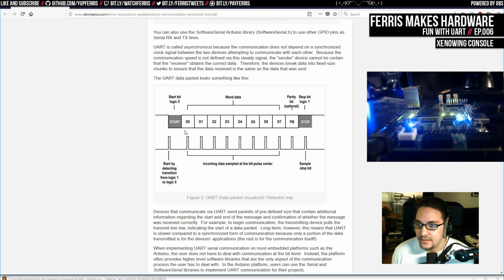And UART is a really simple protocol. You basically have the bit rate here, which is the timing between different parts of this protocol. That's already predetermined. Your transmitter and your receiver just have to agree on that. In this case, I'm just using 9600 baud, which is baseline. It's total crap. I should actually be able to raise that because I think the chip on this board supports up to like 2 megabaud, which would be a lot better. But I think I need to update drivers to do that, and I just haven't bothered yet. I wanted to get it to work before doing that stuff.